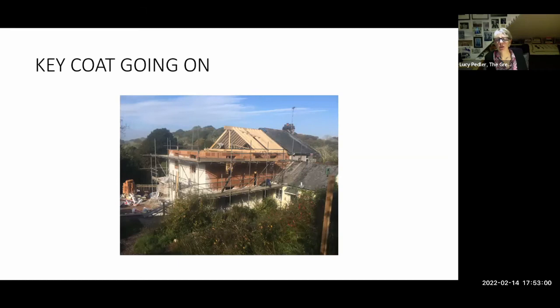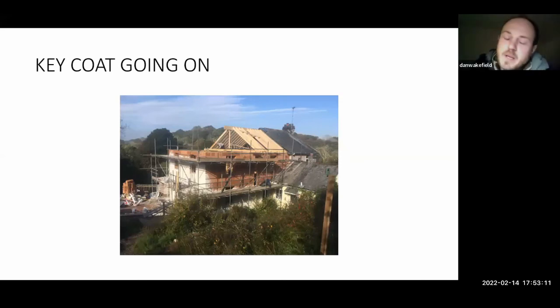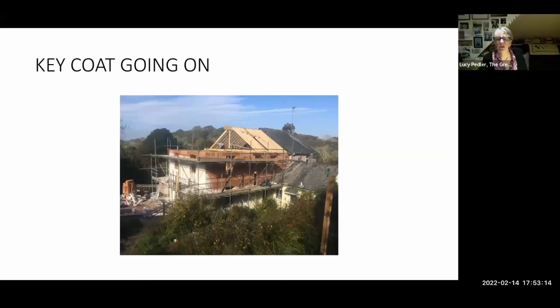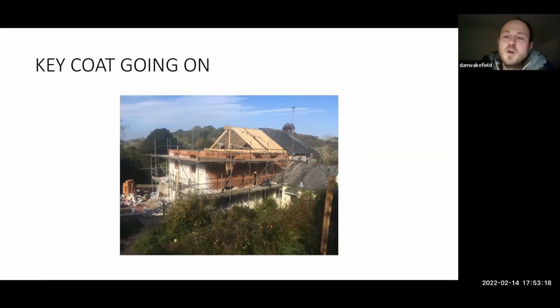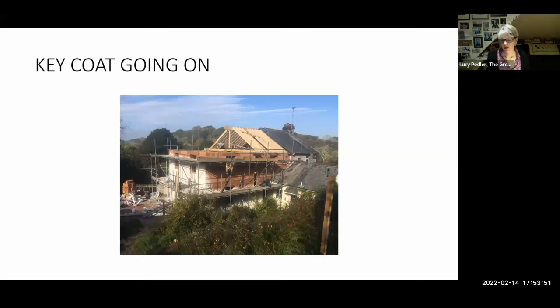CSK says, can the clay and lime be returned to the earth if you bond each block with the adhesive? Doesn't this mean they're not designed for disassembly? I think this was the comment, Dan, you said about returning to the earth at the beginning. It's not really an adhesive. I use that term because it's thin, it's like a grout basically, but it's a cementitious grout. So it's probably the least natural element of the system, but it feels pretty close. I think compared to conventional construction, it's a lot more biodegradable than a lot of materials.